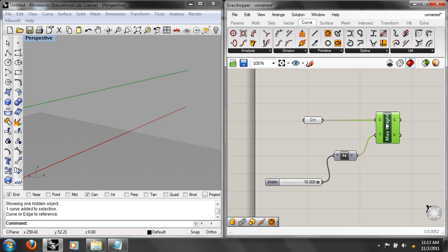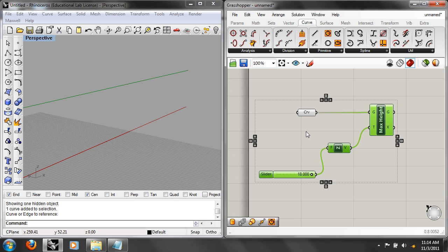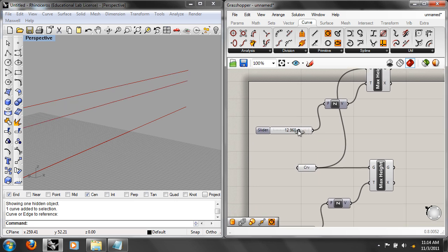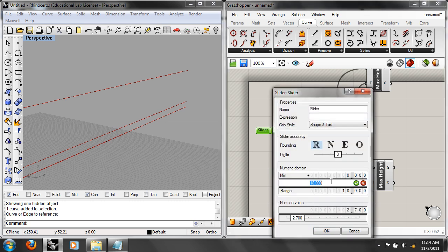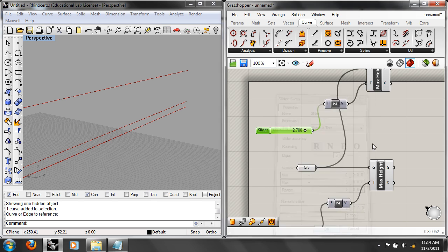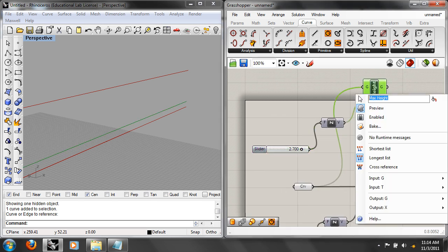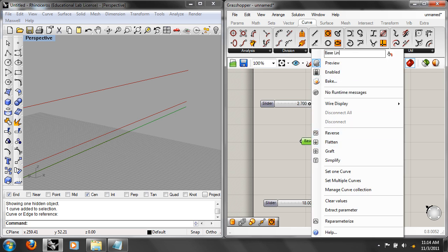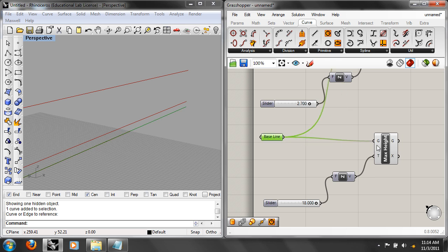It's not some anonymous collection of moves. It's the maximum height. It's a line. It's my datum line. Okay, it's smart. And then let's just make more lines. Take a copy of those, and you can set a different range here. Let's say that the maximum height for the base of the window is going to be 3 feet, 3 units. And let's just call this window line. Okay, so you could rename this too: baseline, maximum height, window line.